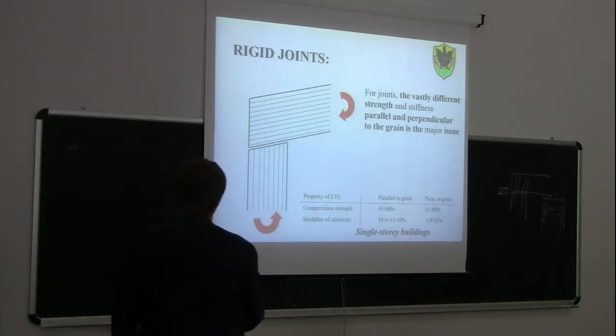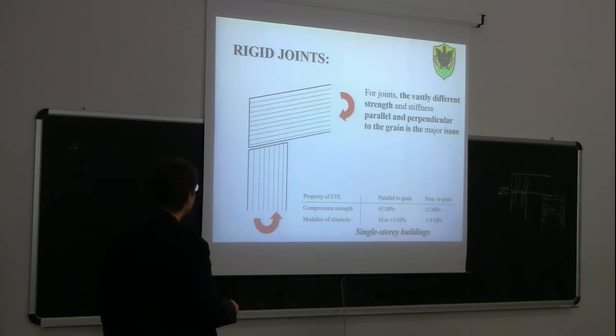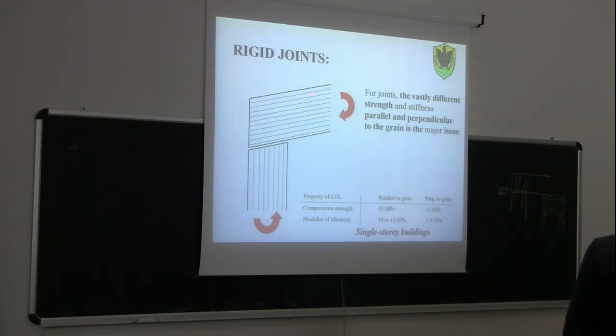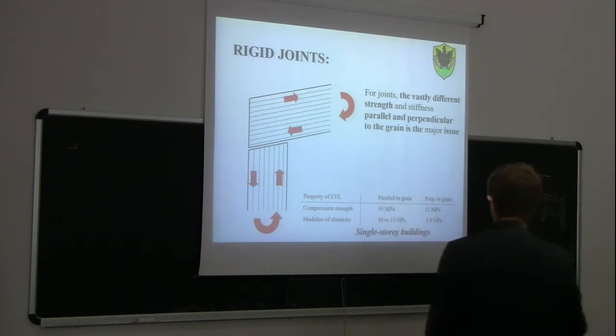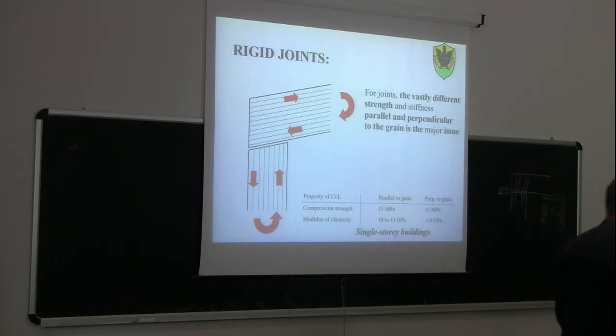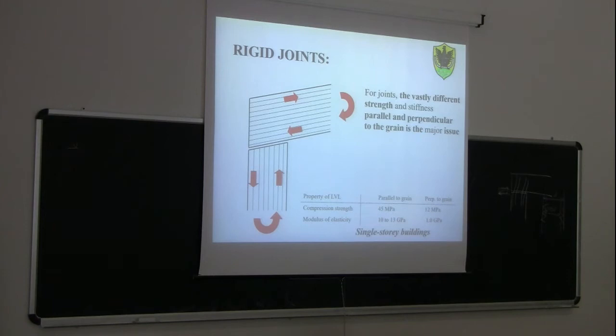That's a huge difference. So when it comes to transferring a bending moment, the bending moment can always be considered as a couple of forces. So this bending moment is a couple of tensile force running here and a compression force running here. The same for this one, tensile force running here, compression force running there. So the first thing to do is to make sure that the tensile force may be transferred from one member to the other. How can we make sure that the tensile force can be transferred between the two members? If here we have a discontinuity, we need to add one element, for example, rods like we did before, or a plate, something continuous that may allow this axial force to be transferred through this continuity. The first thing to do is to make the tensile force able to be transferred, so to make some continuity on this discontinuity here.